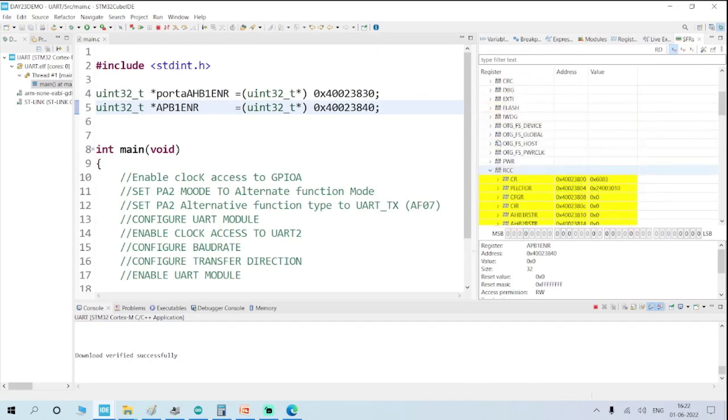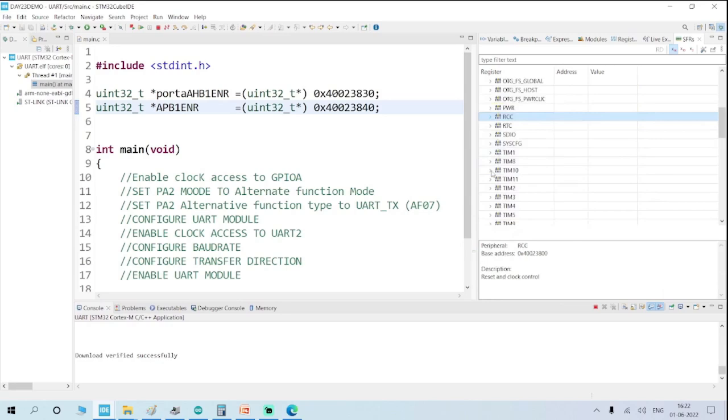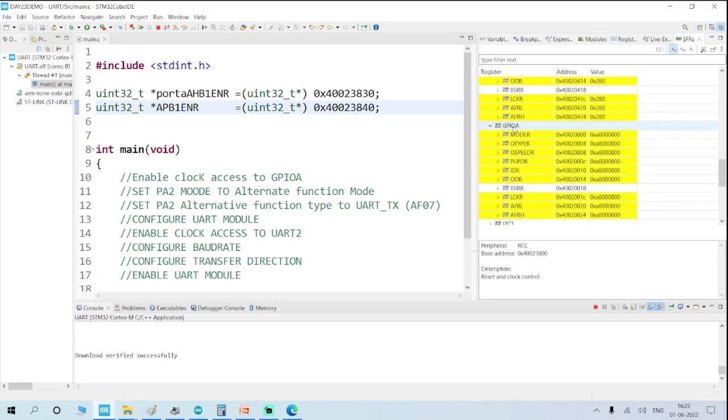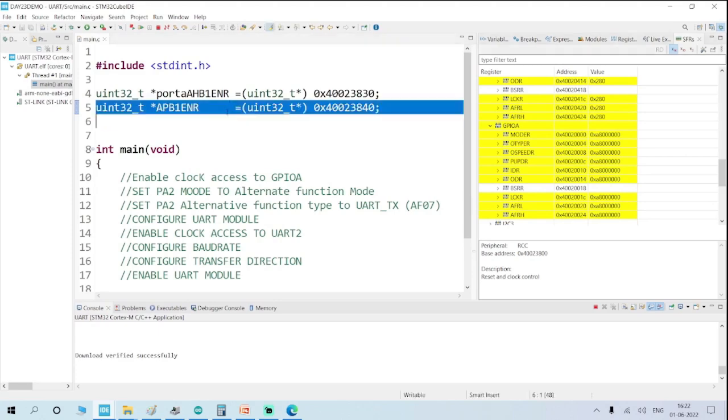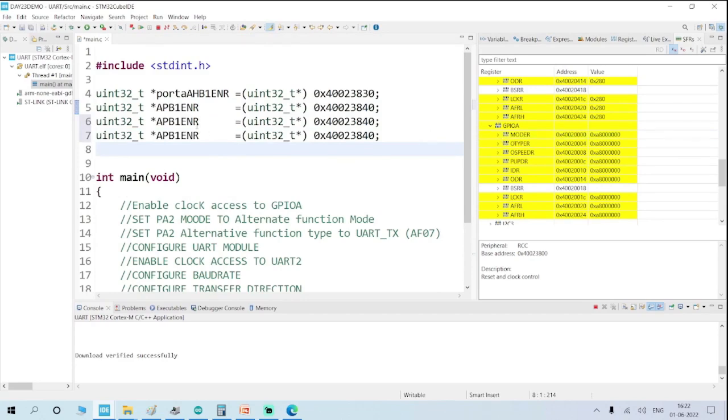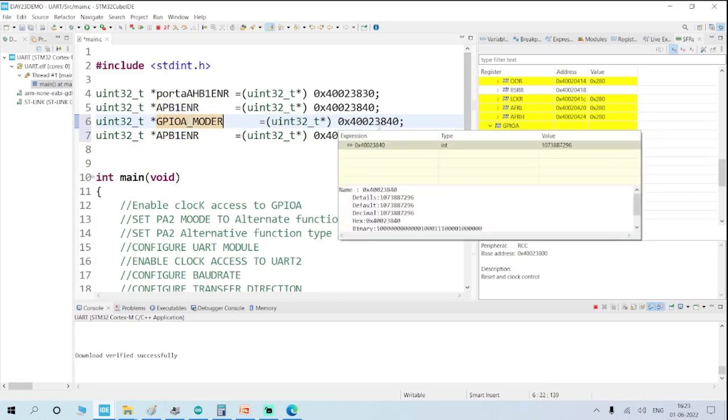So next you need to configure the mode registers. Okay, RCC is okay. You just go for GPIO because USART2 is on GPIO. You have to configure the mode register, and you need to configure the alternate function. AFR stands for alternate function. So just copy this. I just name it as GPIO_MODER. Okay, the value is 0x...